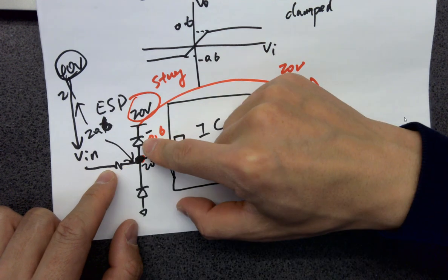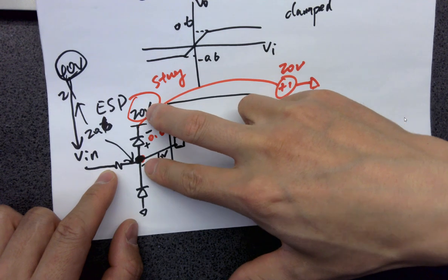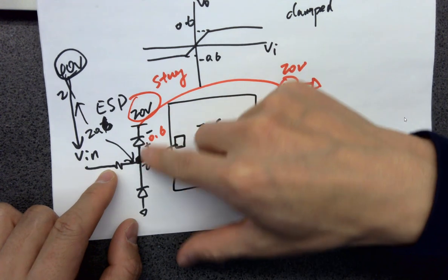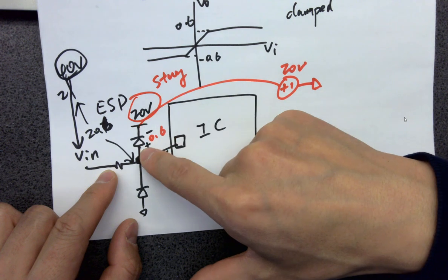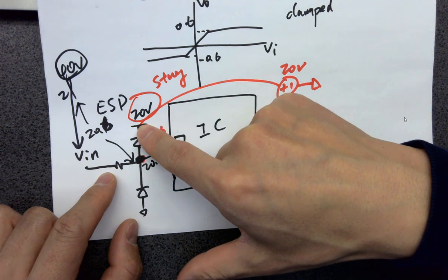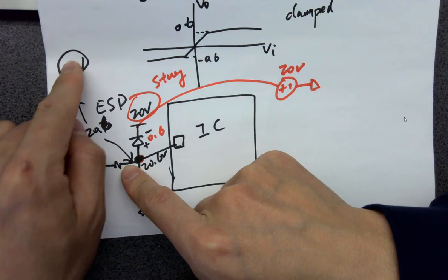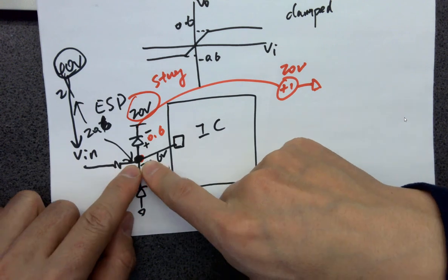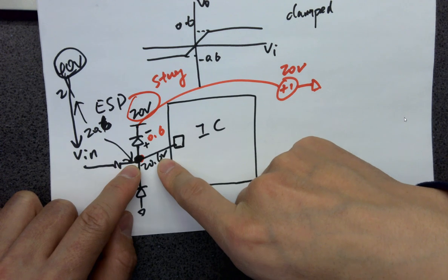That's why we need the resistor here. So for a very short period of time, you get a surge over here, it reaches here, and it creates a pretty big voltage drop, and that introduces a lot of current into the diode, and that current will go through this resistor and create a drop. So most of the 40 volts will be dropped across the resistor, and eventually give you 20.6 volts fixed over here.